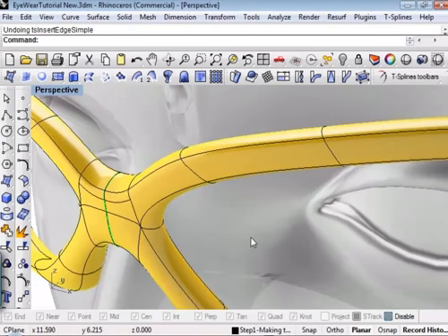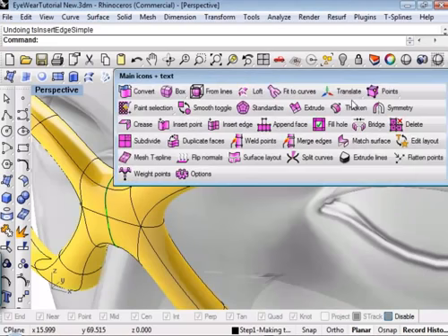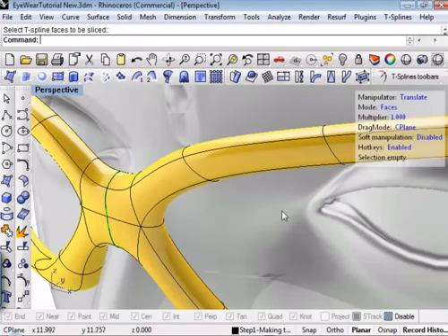There are very few instances in product design where you want something that's actually sharp, because if you zoom in on any object made on any type of modern production equipment, it's going to have a teeny tiny fillet on it. Crease doesn't give you that. Crease actually gives you a sharp knife edge. What I would do instead here is insert a couple edges. Grab my edge tool instead.